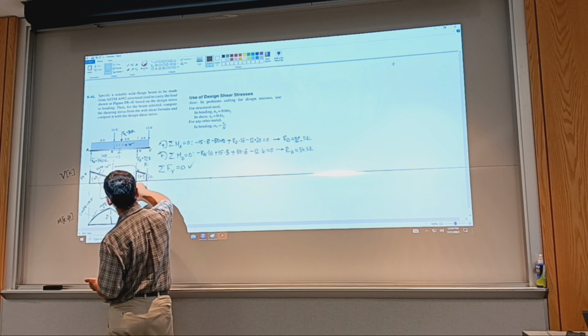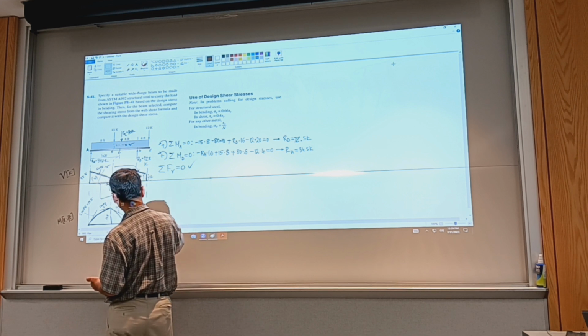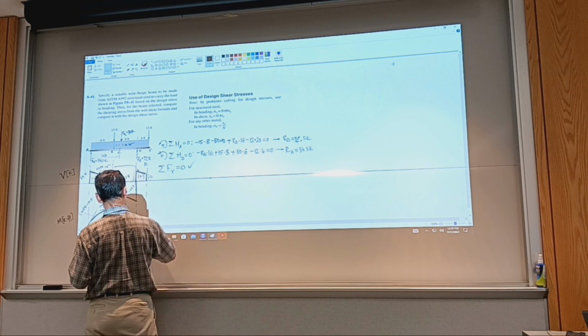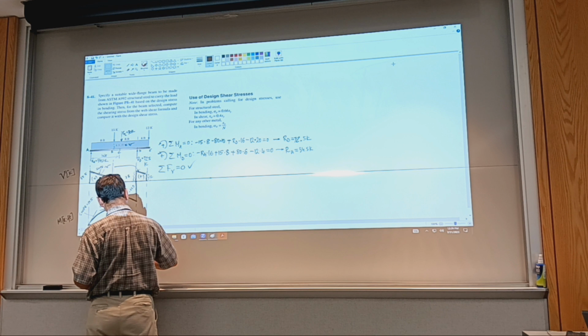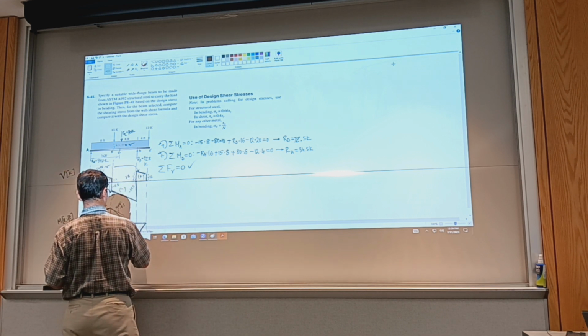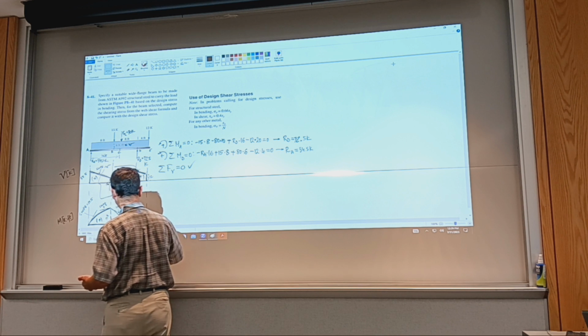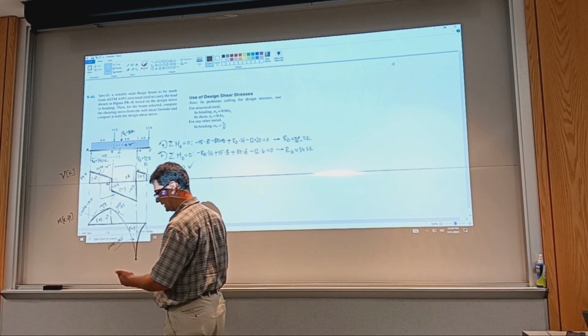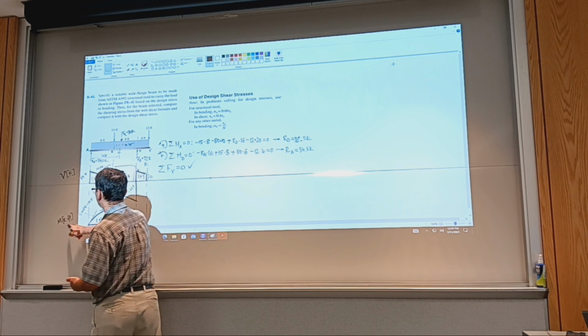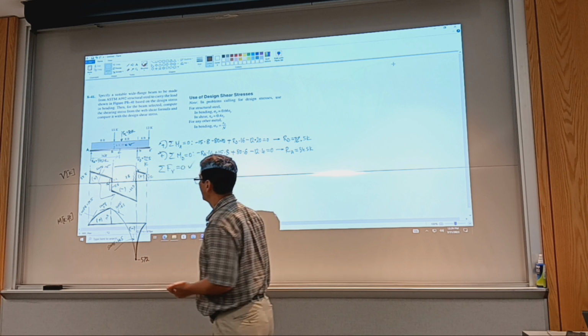So it starts with a positive slope of 28, which goes to a negative slope of 12. So something like this. All right, positive moment, negative moment, maximum here was evaluated at 572. So this is negative 572 kilopound foot.